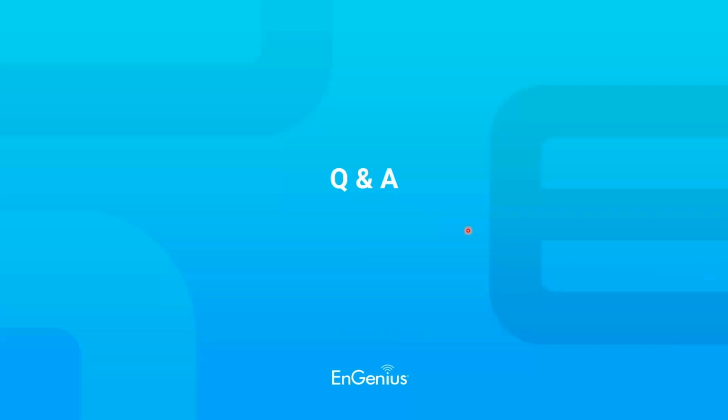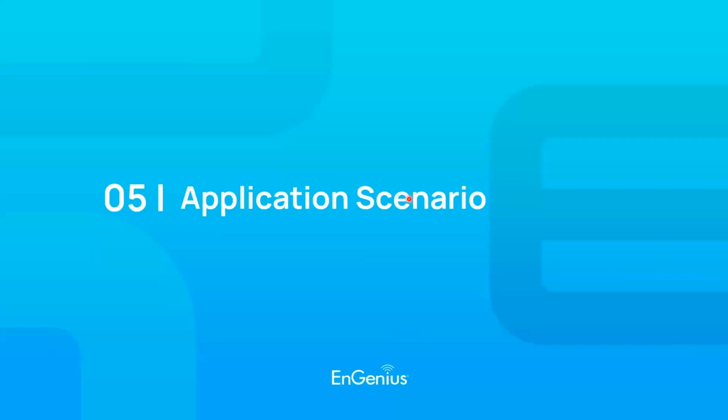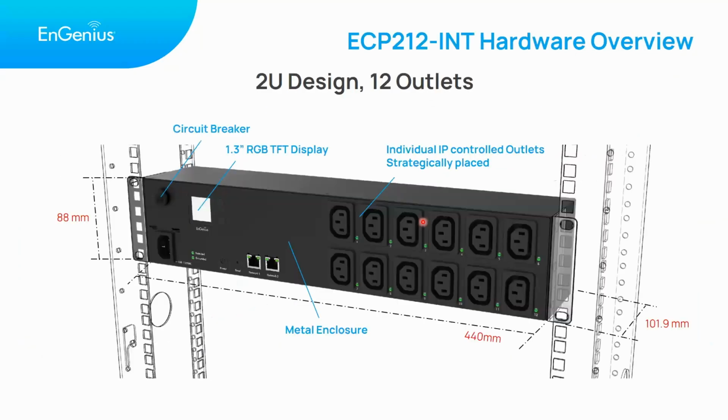PDU, any UK type? So the current PDU that we have has a C13 input. So it has a C13 type of plug, but we have accessories available so that you can change the port to a UK plug. Essentially, you need to plug it over it. You see this depression right here. Once you plug that accessory, the new socket that's over it is a UK plug or a universal plug. That type of accessory can be purchased off the shelf as well. It can be easily bought online or at any hardware store.